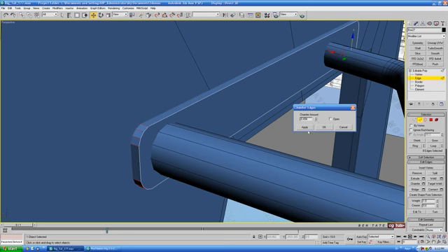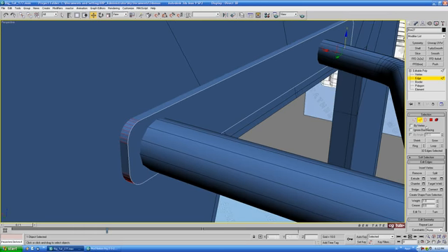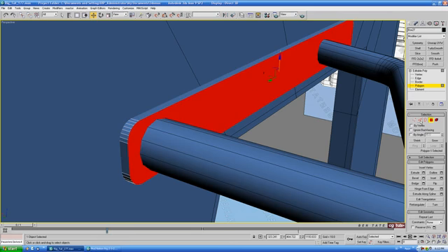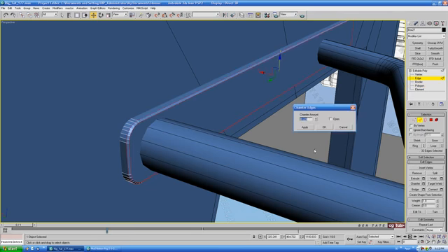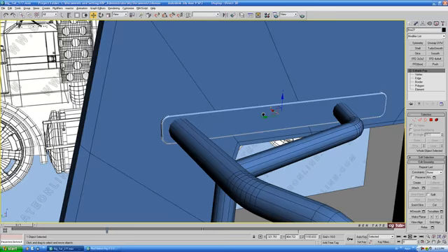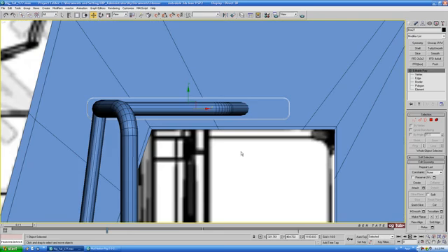And we'll give it maybe a triple here. Okay, so just pretty much evenly space these edges and then hit OK. And to get the front edge there, we'll just grab the front polygon, control click edge, and chamfer it over. And we'll just do that maybe about 0.2 or so. And OK. Alright, so pretty simple for the plates.